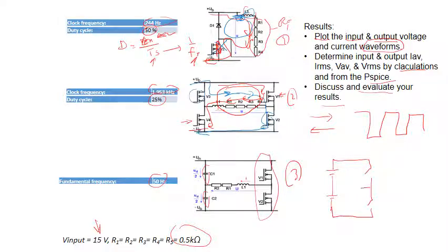Okay, let's assume this is resistance and inductance, this is the load. Now when this switch is on, current will flow in this direction from this supply. This switch is off, so there is no current from this supply. Let me change the color. When this switch is on, this one is off and no longer conducting. The current will flow in this direction. So you can see here currents flowing in different directions, which produces what we also call a square wave. We will discuss this in the inverter part.